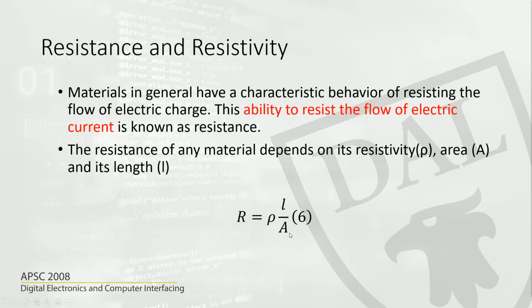So here's the formula. R, the resistance, which is 120 ohms, equals the resistivity, which is on the next slide, times the length, 4 times 10 power minus 2 meters, divided by the area. Area is what we have to find first to get the radius.